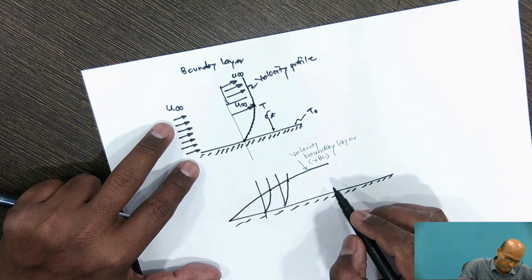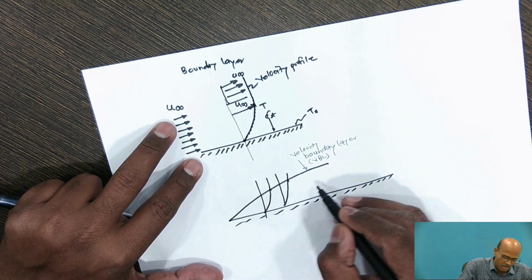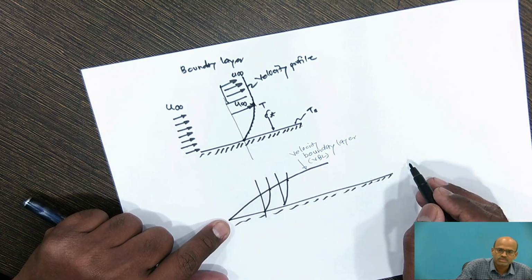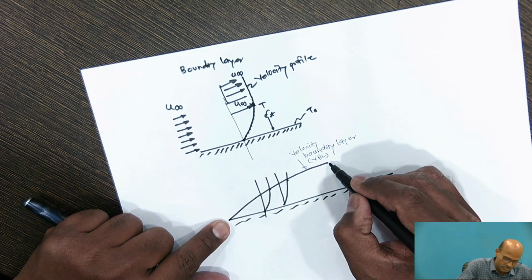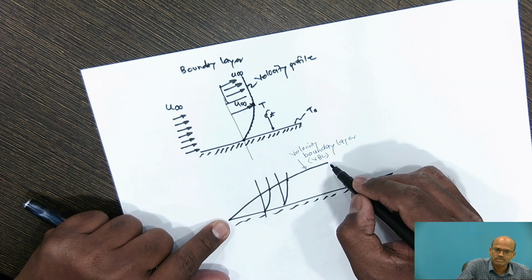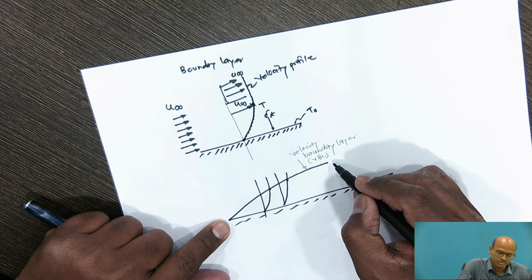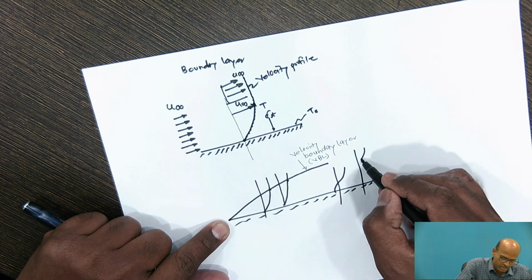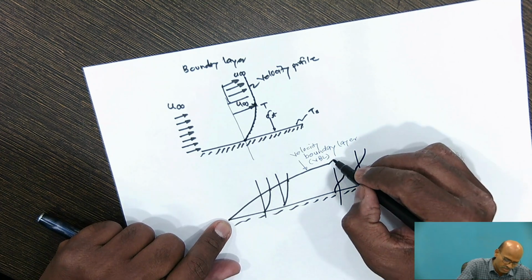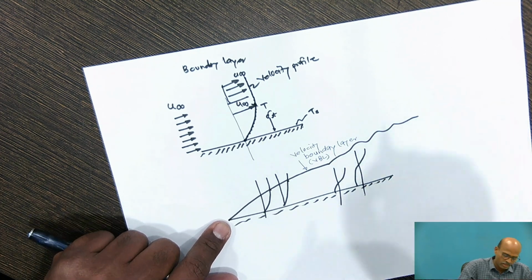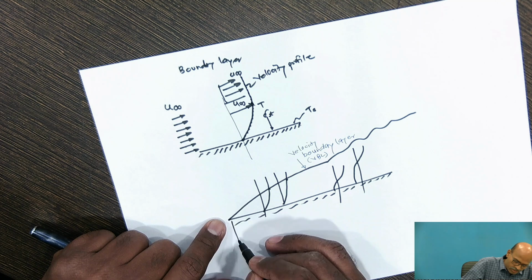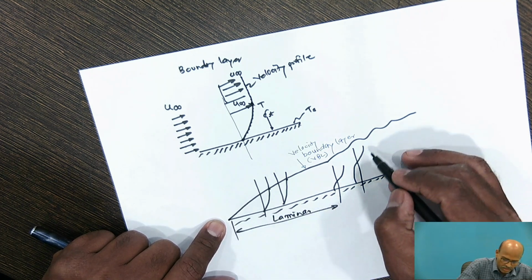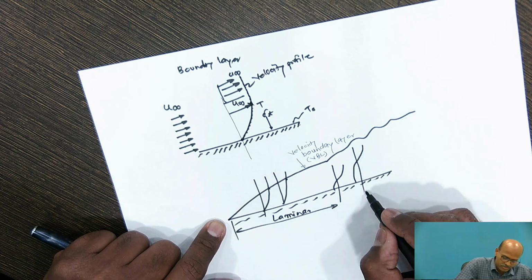Now these boundary layers get disturbed after certain movement along the surface. We will assume somewhere here there will be disturbance or separation of the boundary layer from the surface. Means the boundary layer will be like this, somewhere here, in this fashion. So this becomes turbulent flow. Up to this point you can consider the flow to be laminar, and after some gap it becomes turbulent in nature.